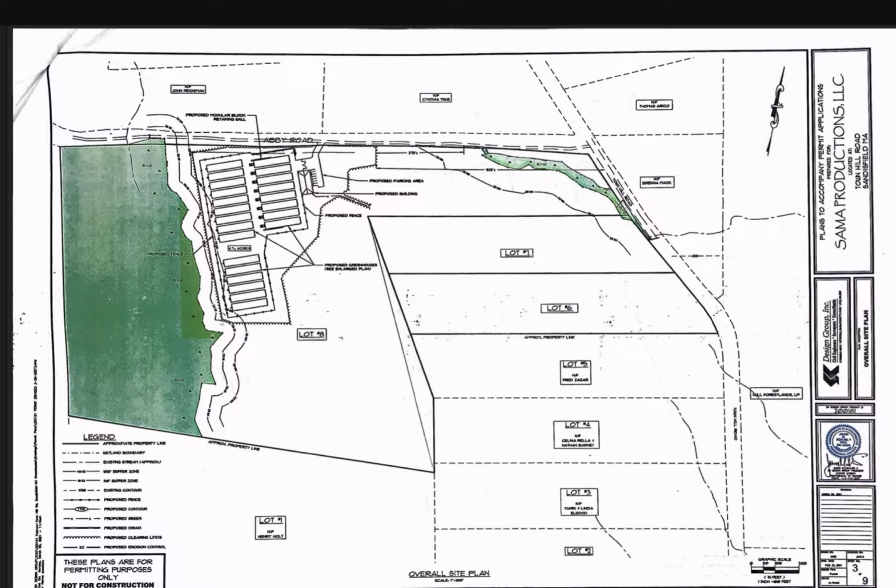In my opinion, that means you're going to have a level of service. So engineers grade level of service at intersections like you got in grade school, A, B, C, D, level of service F would be a problem, obviously. A facility like this based on 10 or 15 employees, I used 15 employees for traffic just to try to be conservative, to try to generate a number.